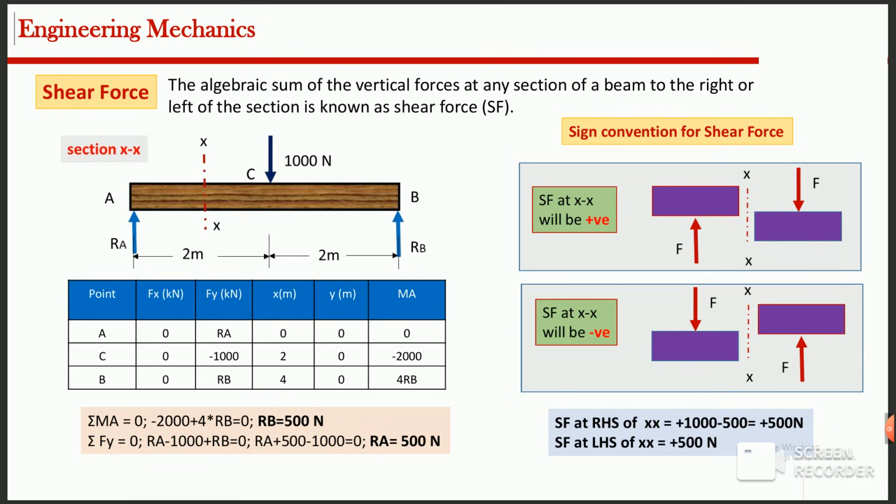If the left portion moves upward or the right portion moves downward, the shear force is considered positive. If the left portion moves downward or the right portion moves upward, the shear force is considered negative. Always remember that sign convention is very important because it determines the shape of the shear force diagram.